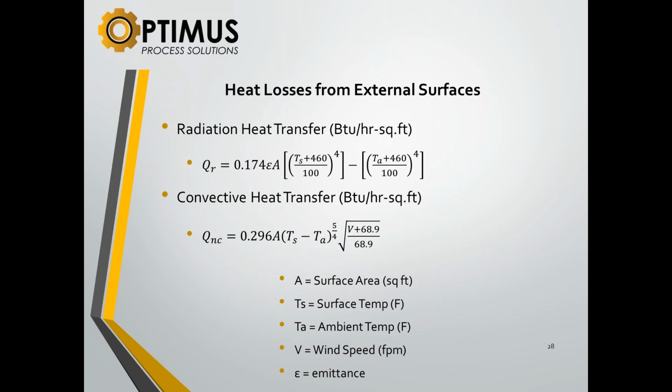There's a factor on there called the emittance, and the emittance is very close to what they call emissivity. It's almost the same thing. When you shoot this with your camera, you have to get the right emissivity to set your gun for. On a kiln, that's usually about 0.79, because of carbon steel, because it's rusted. So it's important that you get the right emissivity. So you might have to just take a thermocouple and put it up on the shell.